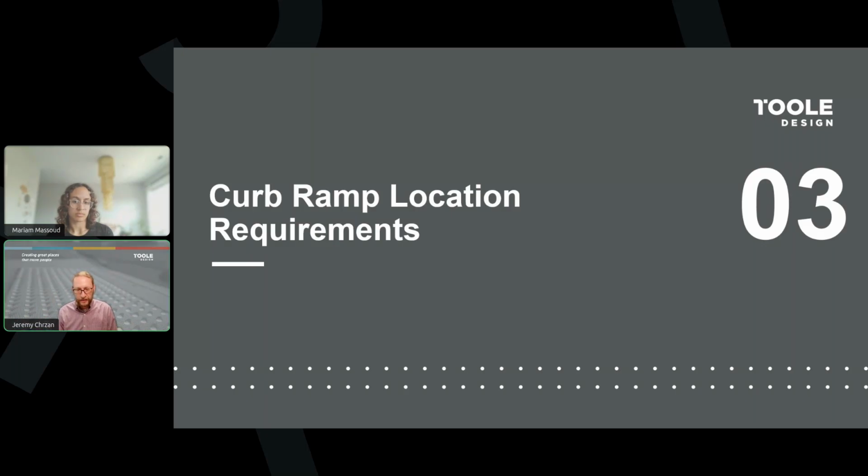There are also some times where there is an existing diagonal curb ramp and you're trying to replace that with two separate curb ramps, and we'll get into that in the technical details a little bit later. But sometimes when you're splitting those ramps into two separate locations, that also triggers the need for creating a little bit more mill and overlay so that that connection can be made accessible. Does that help to answer your question?